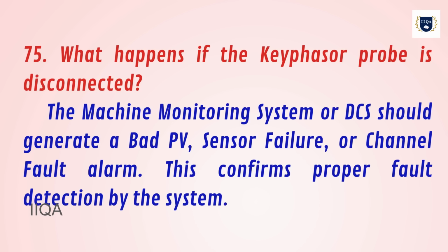75. What happens if the Keyphasor probe is disconnected? The machine monitoring system or DCS should generate a bad PV, sensor failure or channel fault alarm.